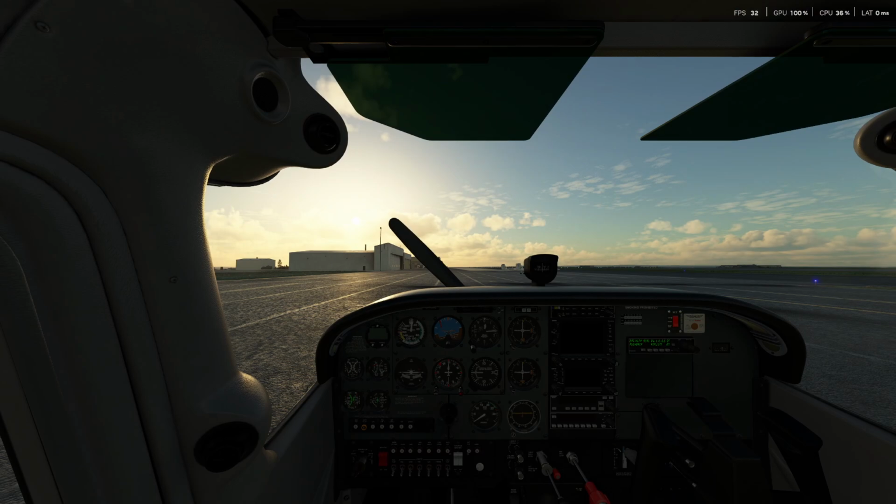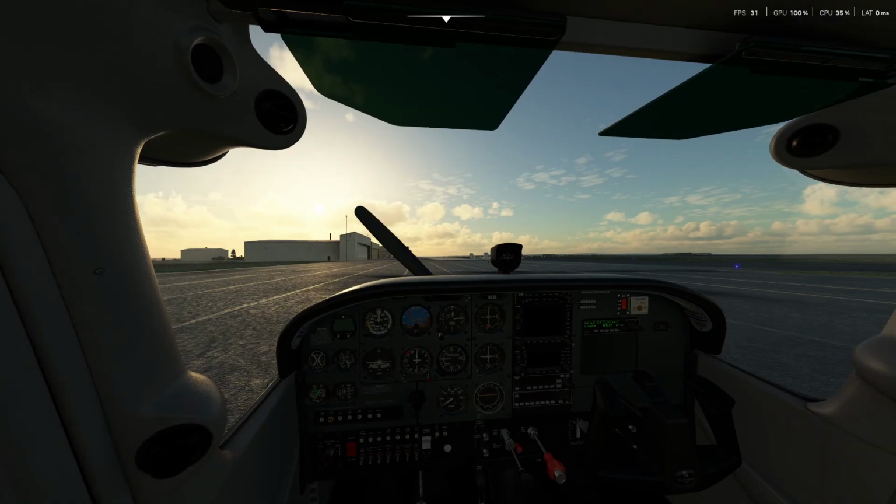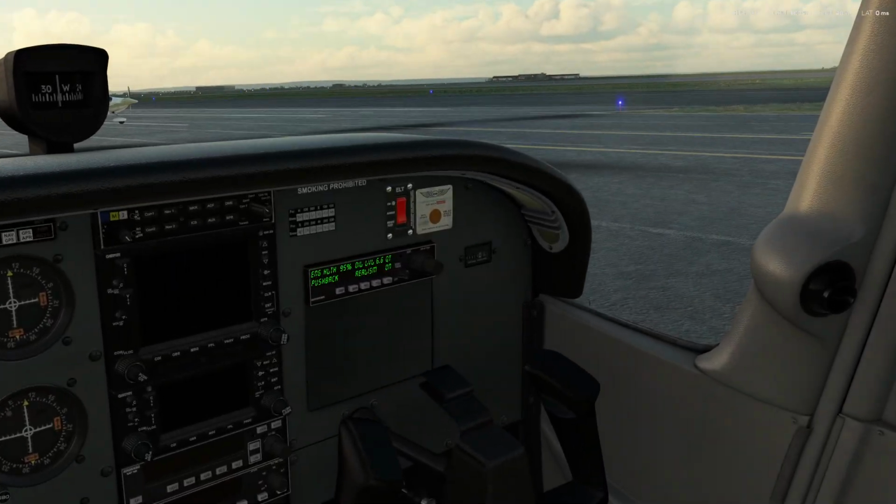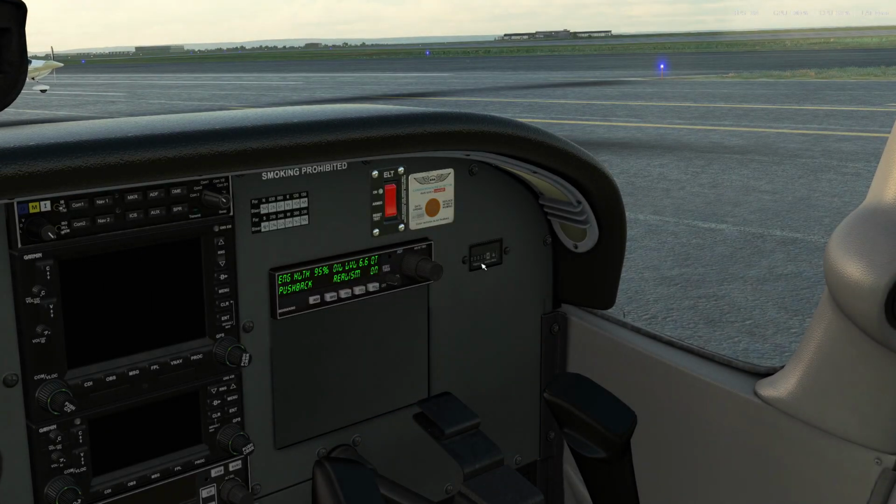Pre-flight inspections complete. Chocks, locks, tow bar, and cowl cover are confirmed removed. They are actually simulated in this 172 default. Cold weather baffles not required. The Hobbs meter is over here. Normally we would record that, but because we're not going to fill out the second page of that pre-flight briefing card, we don't have to write that down.